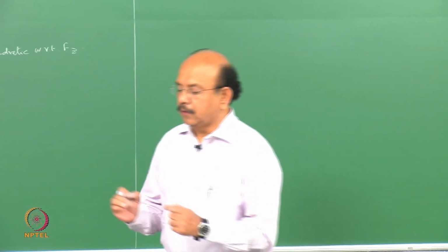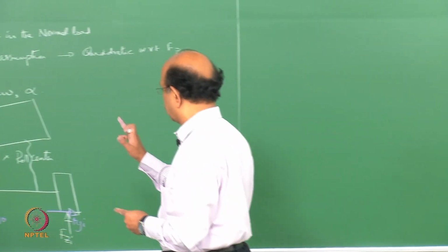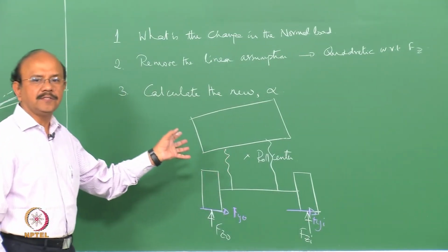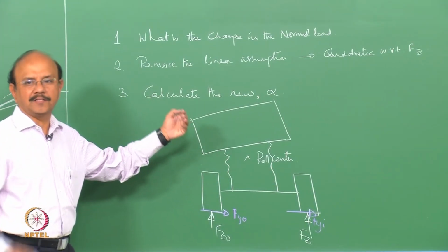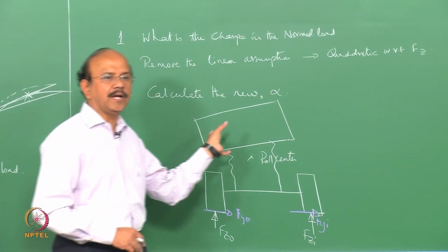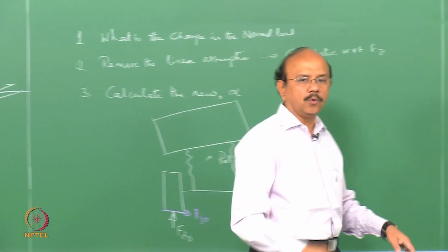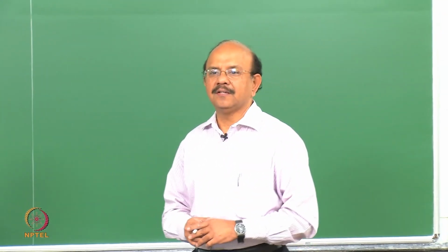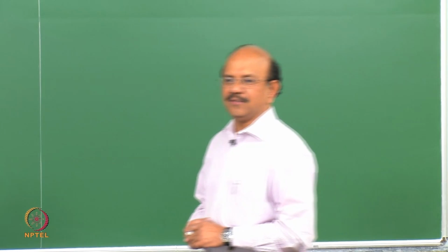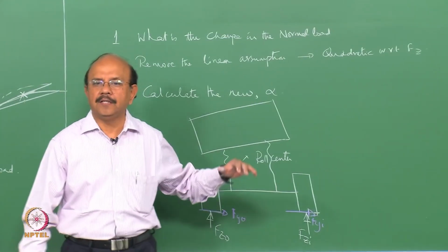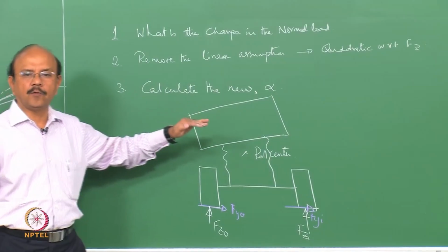Now, the concept of roll center, I'm sure you had heard about this, that roll centers form a roll axis. I know that you had heard about this term roll axis, about which actually the sprung mass rolls. Another way of looking at roll center is the center about which you can split, in very simple mundane terms, the sprung mass from the unsprung mass.